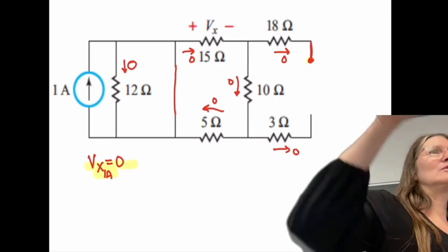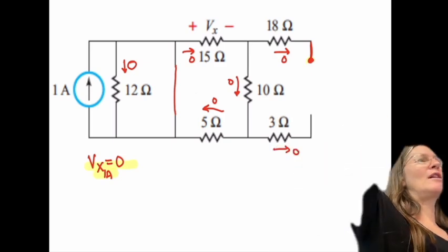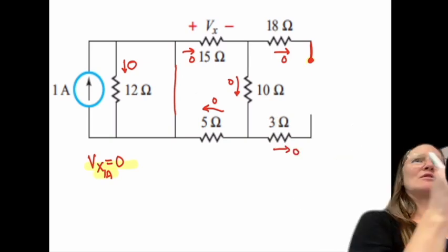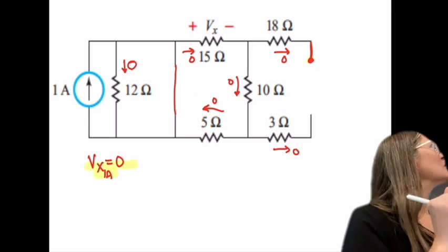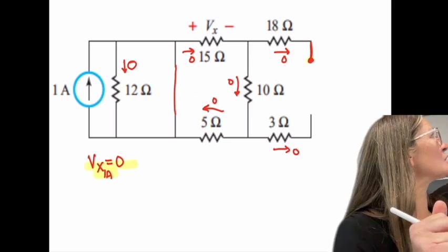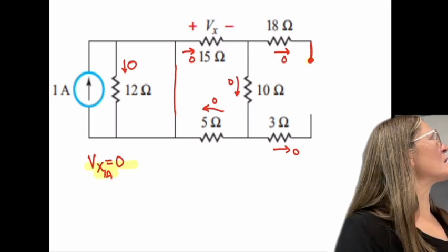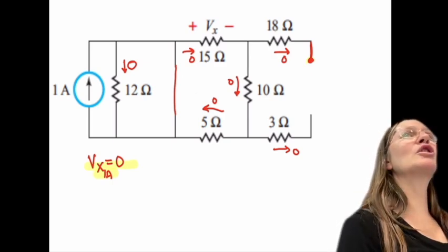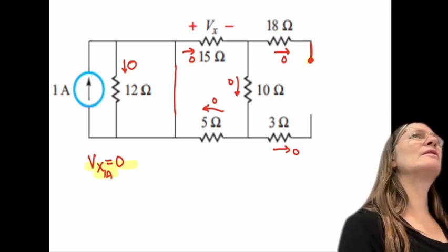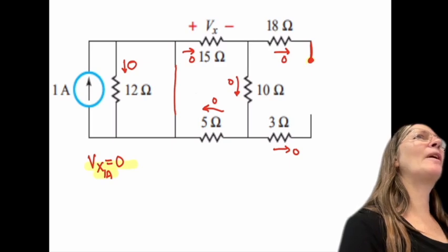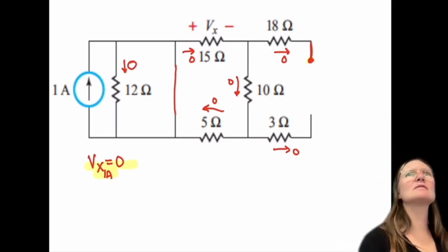So it's like you have a wire, and then I have a resistor. It's kind of even in its own circle. So if you were to take a loop, it would be equal to 0, and then your current would be equal to 0, so voltages across those are equal to 0. Does that help? Okay. Other questions?